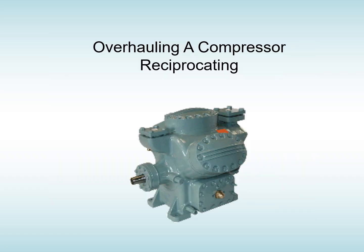We'll take a quick look at overhauling a compressor. In this case, a reciprocating compressor. They're generally the only ones that you're going to overhaul on site. Screw compressors are just a mass of bearings, and they're better off being removed and sent back.